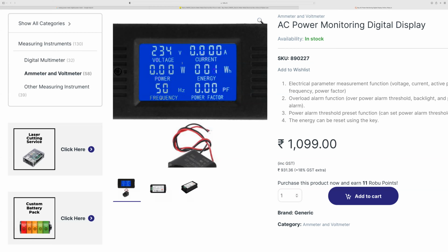The energy input is measured in watt hours. You need to convert it to kilowatt hours, multiply it with 10 power minus 3. So everything is there. But this is not how generally a digital meter looks like. Outside your house, you will have a small green color display with different kinds of knobs. You can see only one value at a time. You can either see voltage or power factor or current or energy.